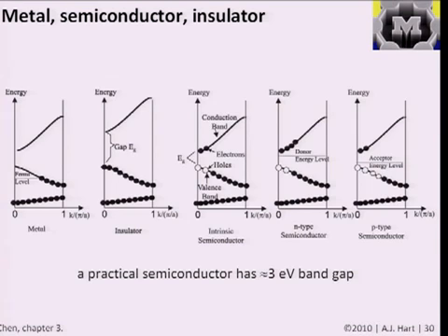When you do that, it will shift this highest occupied level up or down. What that will do is increase the concentration of free carriers in one region or decrease them in another. That really forms the basis of how we make things like microcircuits, where you can add small amounts of doping in one level or another and modulate the properties. So that's really what's special about semiconductors.